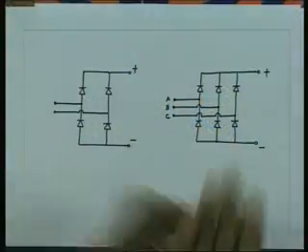There is something known as the maximum power that it can dissipate. In other words, all the devices are thermally limited, because at any given time the power loss taking place is the voltage across it times the current flowing through it. As the power loss increases in the device, the junction temperature will increase, and if it exceeds a certain value it will fail. This is what is known as the thermal limit or the power limit.